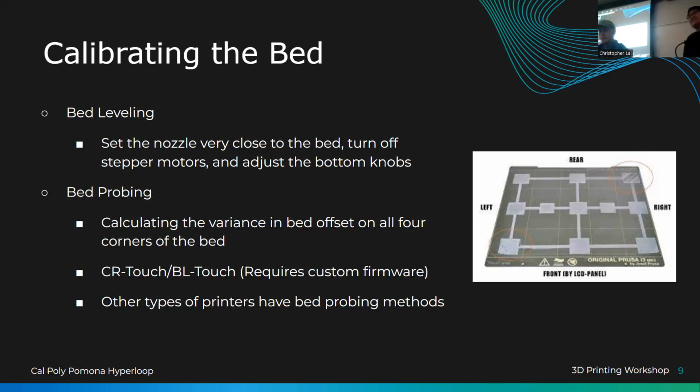Yeah. So when you get good at working with 3D printers, you kind of develop muscle memory. When we don't give you a bed probe, it's harder for you guys because you have to manually level. But for bed leveling, you can get good at eyeballing how close the nozzle is to the bed on all four corners, and you can kind of just do it automatically. That also is the case for feeling how high the nozzle is above the bed. When it prints that first purge line on the side, you can feel if you've leveled it correctly or not just by touching the bed.